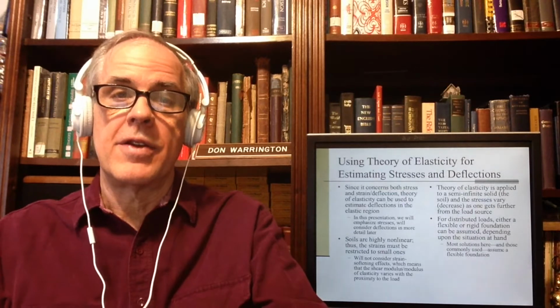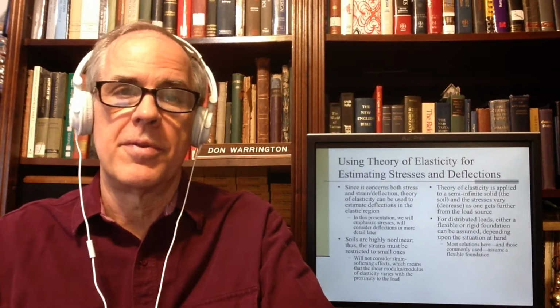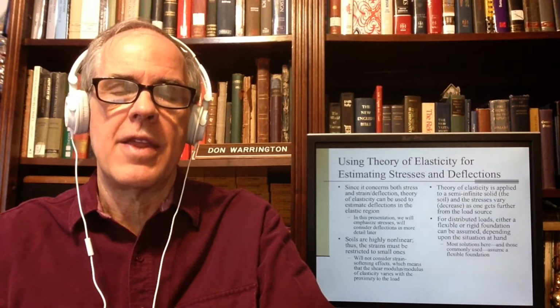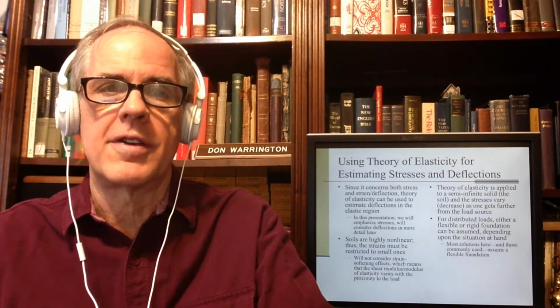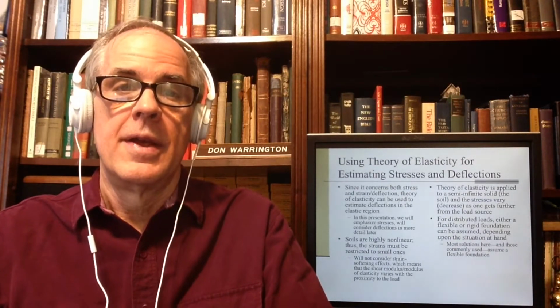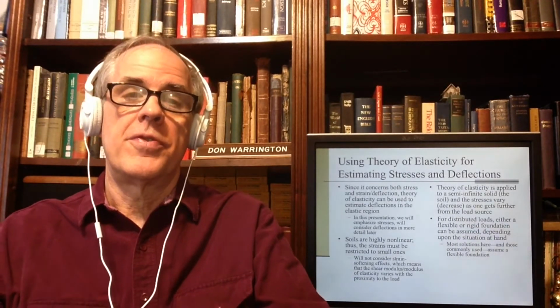We do talk about point loads, but most of our loads are distributed. The other thing is the relative flexibility of the foundation relative to the soil. This is particularly important for deflections.